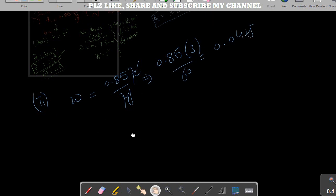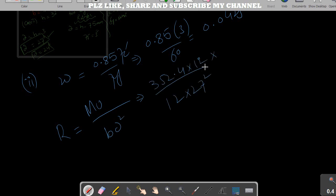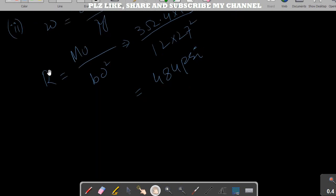This is omega, and from this I will calculate the value of R, which is Mu divided by b d squared, the value into pounds, so multiplied by 1000. We got the value which is 484 psi, right? The value of R is in psi.